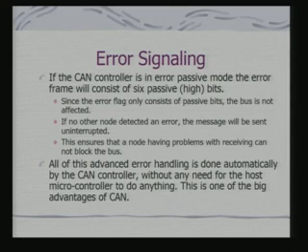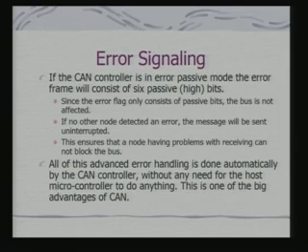And since you are sending any kind of request or data with an identifier which is not linked to the node, but linked to the meaning of the data, there may be other nodes which may satisfy your request for the data. That is how the complete operation can go on even with the failure of a single node. Is this clear? So, this advanced error handling makes CAN a very attractive protocol for